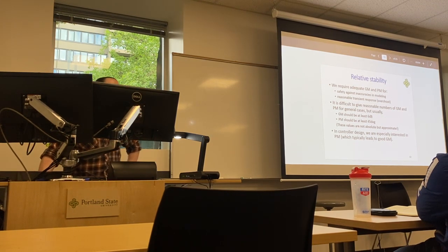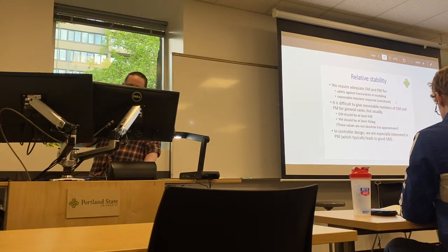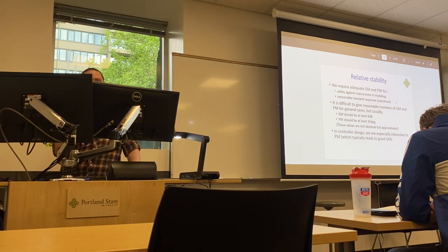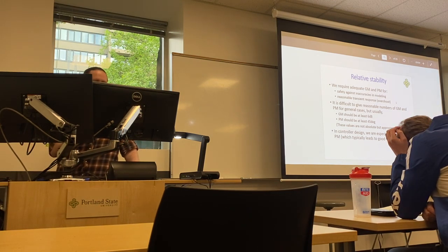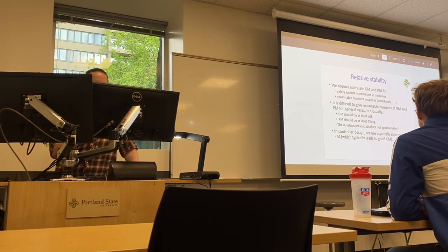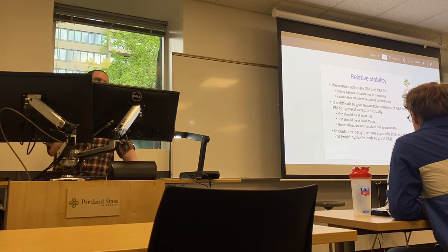And it says here, if we have good phase margin, it usually leads to good gain margin. But I also want to reiterate, we can have good phase margin without having a positive gain margin. It is possible, and it'll probably get brought up later, but I want to just reiterate that just because you might see negative gain margin does not necessarily mean that we are not stable.